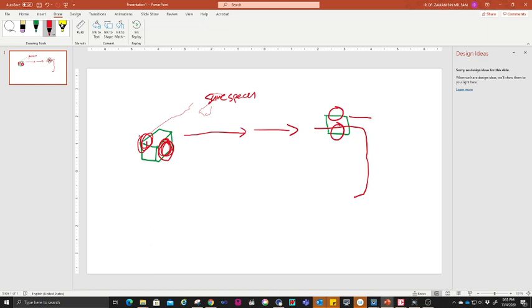If you turn the motors with the same speed, it will still go directly forward. So what you need to do is slow down this wheel, or maybe stop it, and then if the other is still moving, it will turn. After the turn, you have to turn this wheel back on, then it can move forward again.